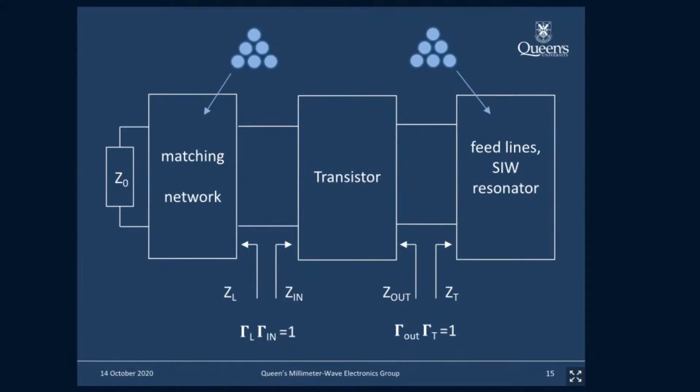Well, as I mentioned before, if you have a droplet of, say, water with an epsilon R of 81, and your substrate has a lower relative dielectric constant of, say, 3, 4, 5, and you just put a droplet on top of a transmission line, you will change the wave propagation velocity enough. That will tune the transmission line. And when you tune that transmission line, the frequency at which this condition is satisfied will change. So then you change the tuning frequency of the oscillator, right? And you can put droplets on the matching network on the output, and then you change the frequency at which this other condition is satisfied. And so we did some experiments with that.